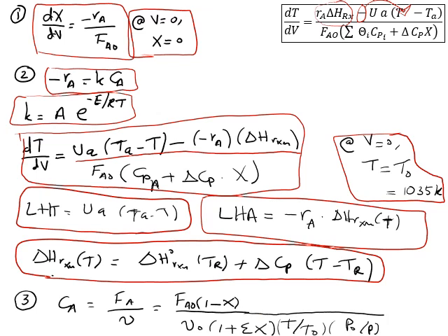Okay, good. Can I simplify? Yes, I can. Well, it's a plug flow reactor, so this guy can go to 1, because I'll assume negligible pressure drop. T is variable, so I have to keep it, and the rest stays the same. Therefore, I'll write an equation for Ca as follows. If you allow me, I'll use the top part.